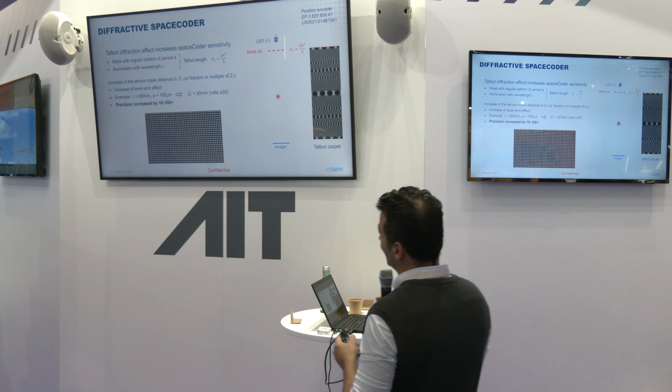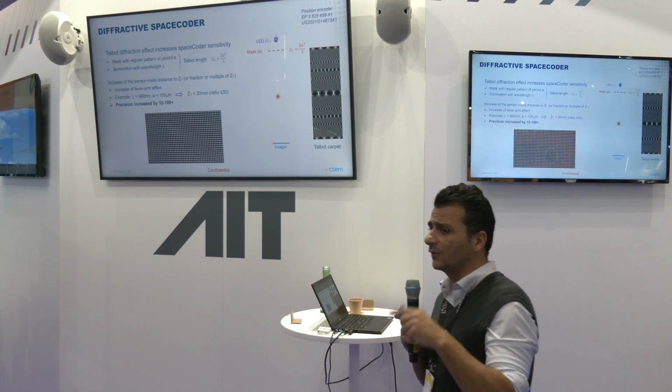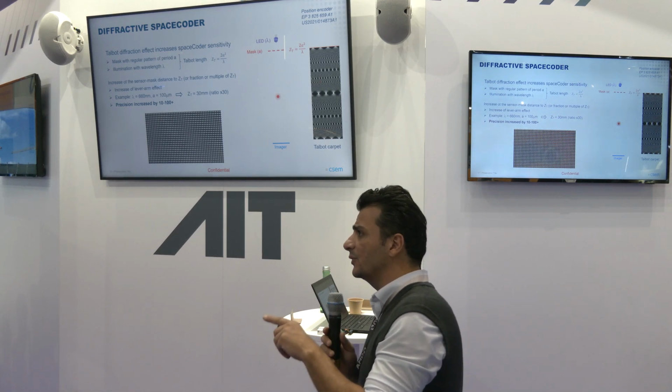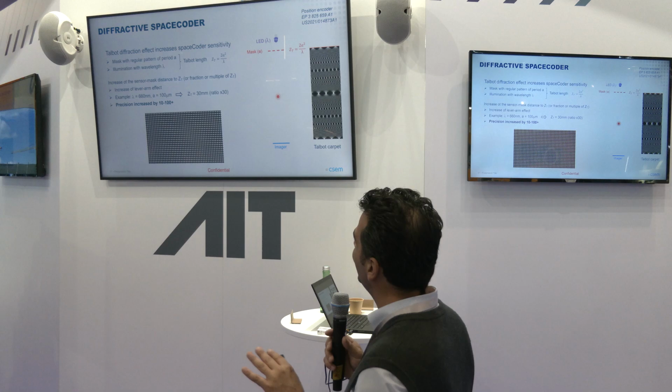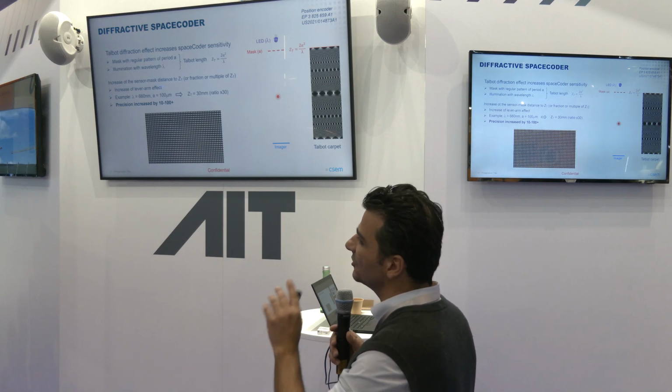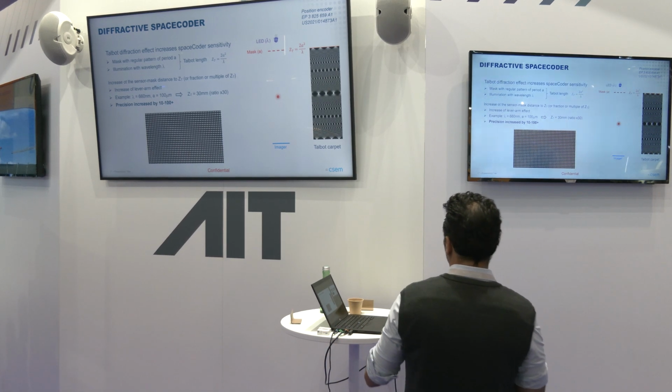And with this type of system, I'm able to reduce the projected error from the sensor, which is on the order of magnitude of 10 nanometer for a 5 micron pixel, to something which is sub-nanometer, as you're going to see in the next slide.